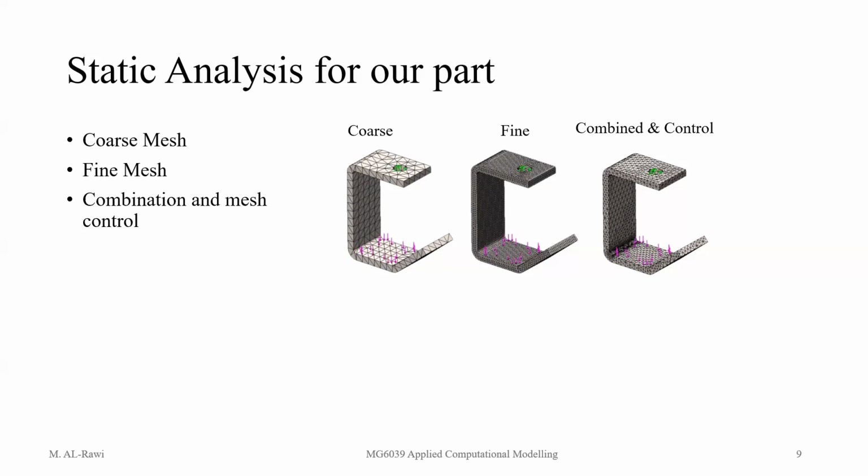because we believe this is the weakest area and we want to see what will happen to it. How do I know that? Because the initial results tell me the maximum stress concentration occurs here. So technically for me this is one of the weakest locations where that bracket would break. Then I focus on it to reduce time and concentrate on it.